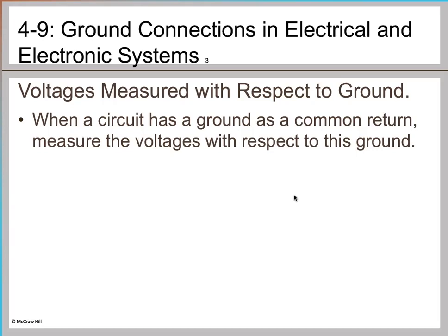So in both cases, let's maybe first talk about the op-amps. You always measure the output voltage in inverting and non-inverting op-amps with respect to ground. So that's how you measure the voltage with respect to ground. And the same in the transistor also. If you're measuring the voltage at the collector, then also you measure with respect to the ground.